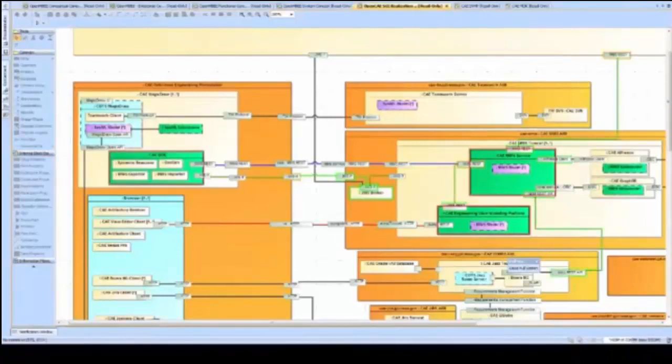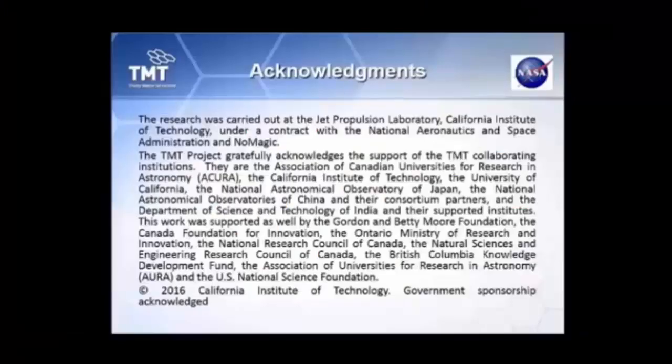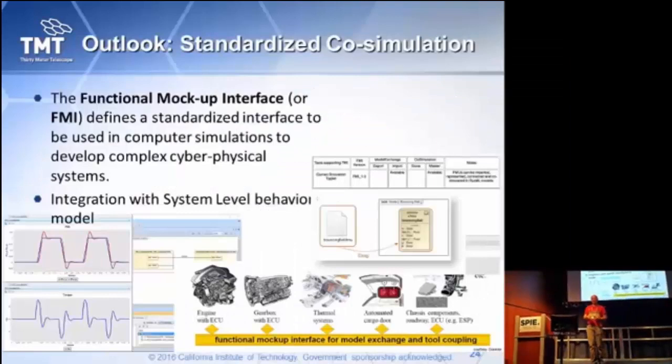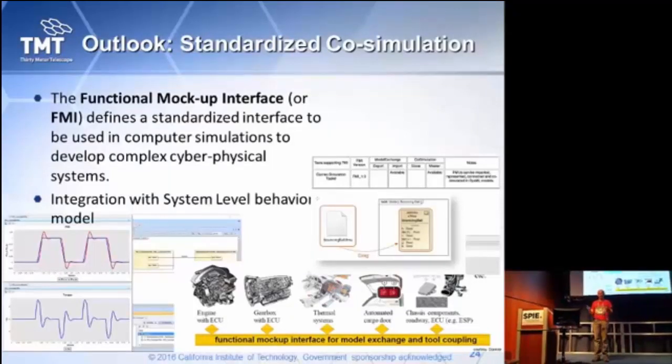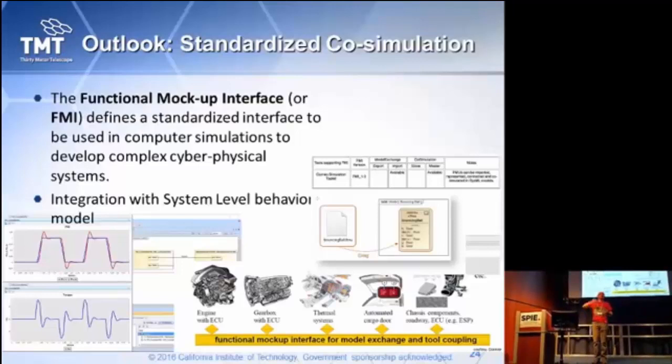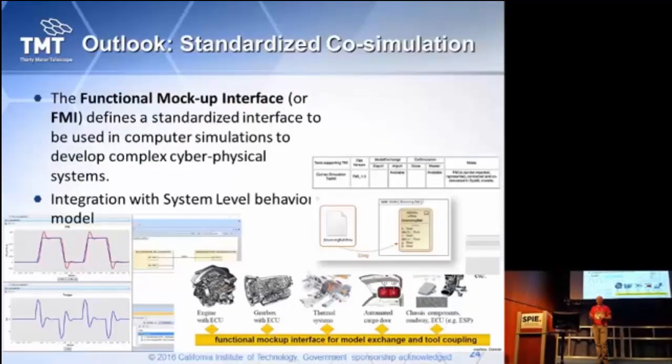Now, I'm very interested in this. At the moment we have system level simulation, which is mostly SysML. But over the last few years, the FMI, the Functional Mock-up Interface standard, has gained a lot of popularity in industry for co-simulation. You would have the architectural model like SysML as the hub, but then you would delegate or outsource all the analysis, particularly analysis, to various tools. It would not be in the SysML model. At the moment there are more than 80 tools already supported which provide an integration through FMI and SysML.